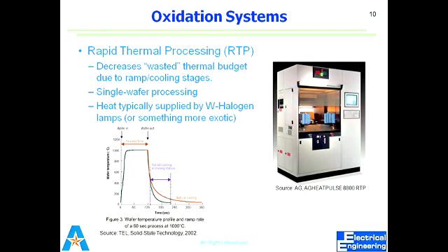At the same time, your oxidation rate increases, because you can heat it up to high temperature in a few seconds. At high temperature, the oxidation rate increases. We talked about yesterday that at high temperature, the oxidation rate increases. So that's why this RTP has got a benefit over the vertical furnace. Now, one thing is that it processes a single wafer at one time.